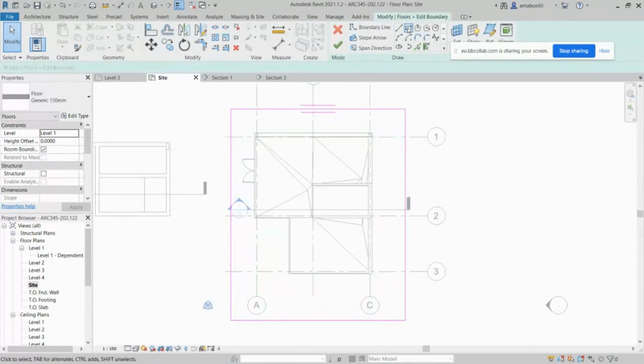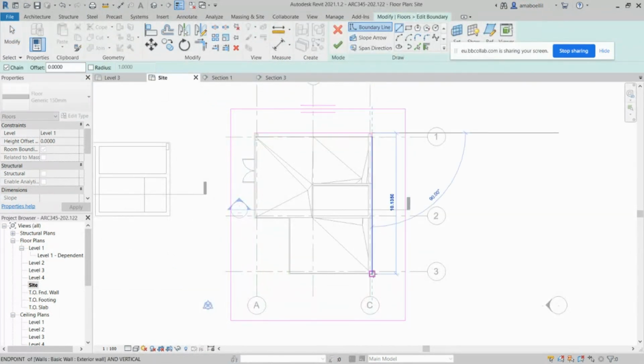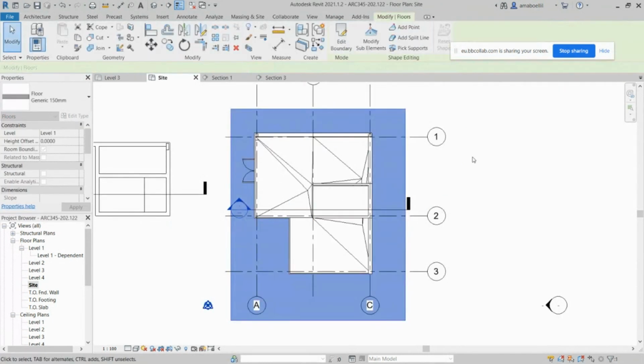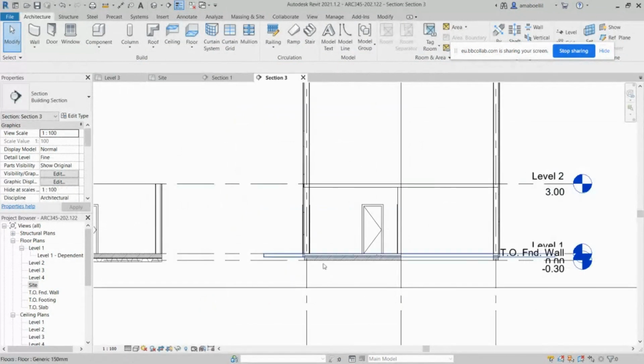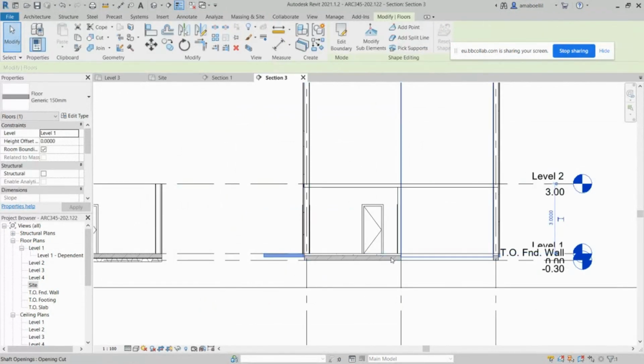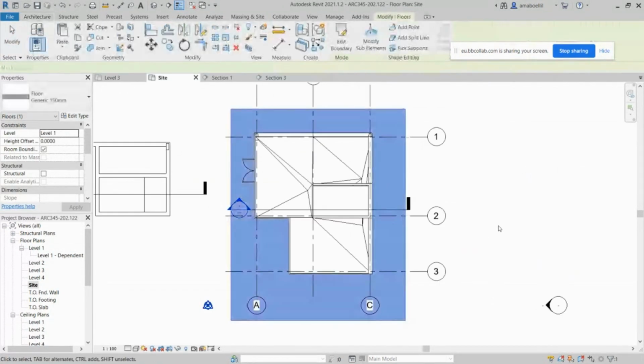You can come here and start to initiate also the other internal element like this and hit OK, so that you are subtracting that, so that they are not overlapped with the inner building. You see that this is surrounding the building and the inner slab is still neat and with no overlapping, because to eliminate the warning that we have seen in the beginning.